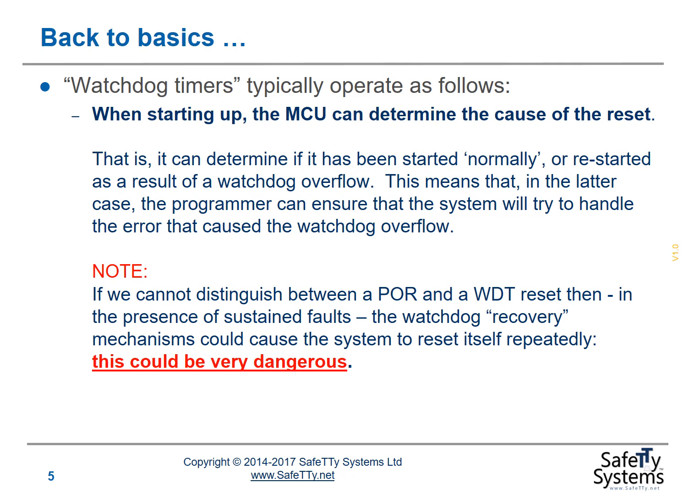When starting up, the microcontroller should be able to determine the cause of the reset. That is, it should be able to determine if it's been started normally or restarted as a result of a watchdog overflow. If the microcontroller has been started as a result of a watchdog overflow, we can then react to the watchdog overflow in an appropriate way.